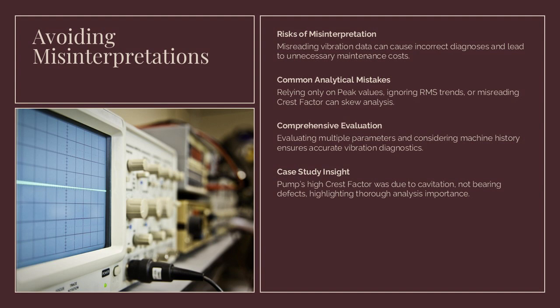A case study example: a pump exhibited high crest factor, initially suggesting bearing defects. However, further analysis revealed intermittent cavitation events causing transient spikes. This underscores the importance of comprehensive analysis and contextual understanding in vibration diagnostics.